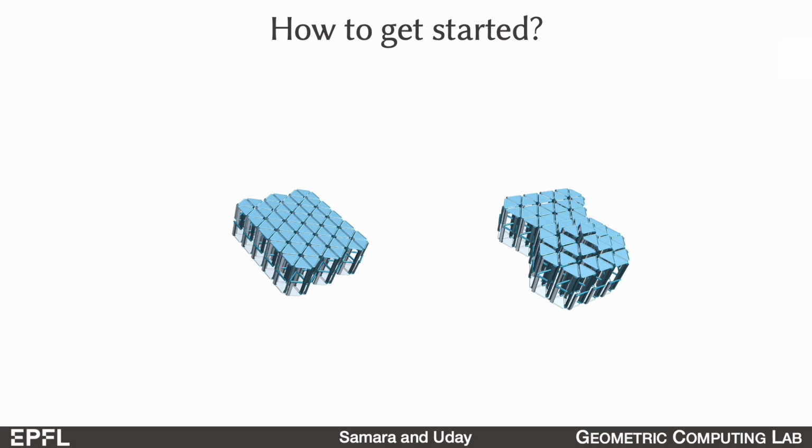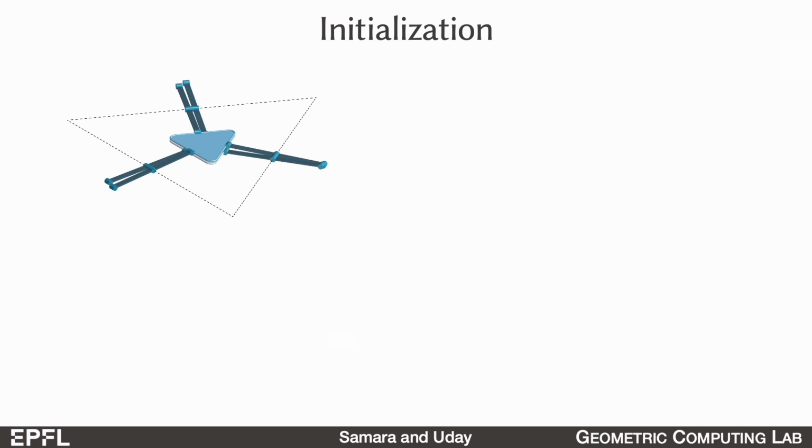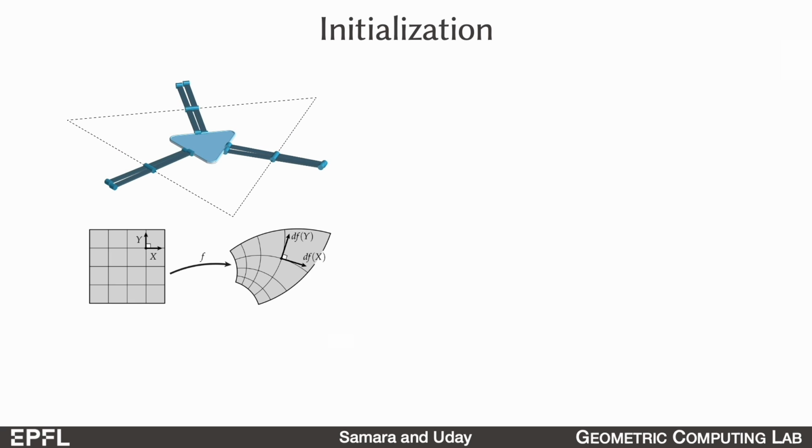The first step of our design optimization is to find a good initialization of the height variables and the 2D shape of the compact state. Both of them can be jointly computed using surface parameterization techniques, and in our case, the conformal flattening. Notice that a single unit always expands or contracts isotropically, that is, uniformly in all directions. A conformal transformation consists of local rotations and uniform scaling, but not shearing. This exactly matches how our unit cell behaves in plane.